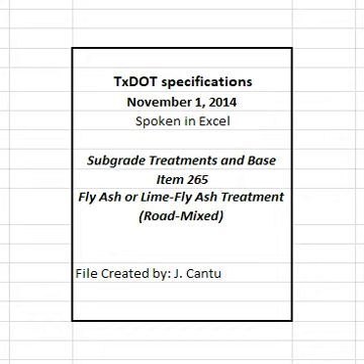Seal the clipped surface immediately by rolling with a pneumatic tire roller until a smooth surface is attained. When finishing treated base, use a steel wheel roller before rolling with the pneumatic tire roller. Add small increments of water as needed during rolling. Shape and maintain the course and surface in conformity with the typical sections, lines, and grades.